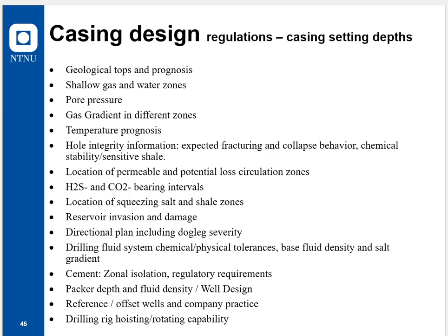So we have a good starting point for our tubulars, selecting also setting depths in the different formations from many of these offset wells, and making it the first run to see, okay, let's try this design, does it work, or do you need to adjust either the setting depth of the casing or change the casing type entirely for each section.